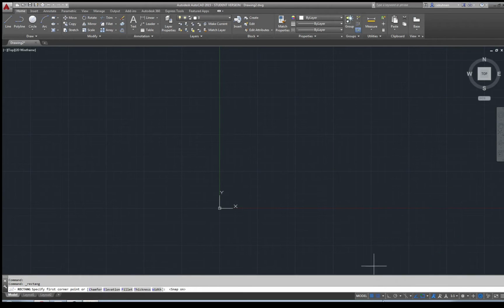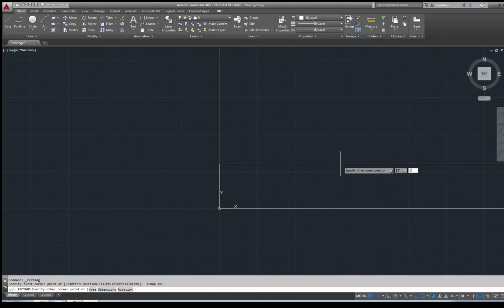So I click on the grid snap. For example, I start drawing from this point, and you see as I move my mouse to the right, the width is being updated. If I move the mouse up and down, you see the grayed out numbers being updated. So this gives me an idea of what's X and what's Y. So my room is 12 feet wide, which is X, tab, and then 10 feet and enter.